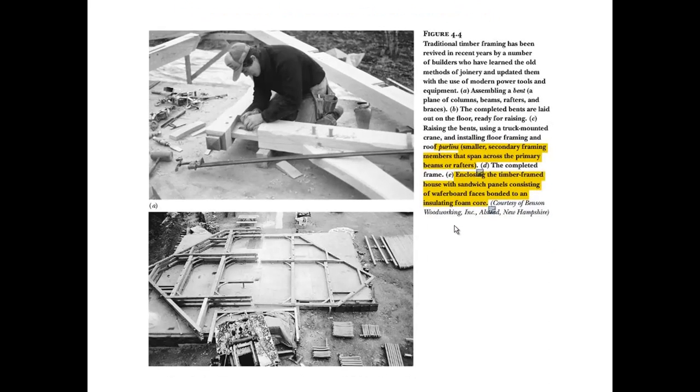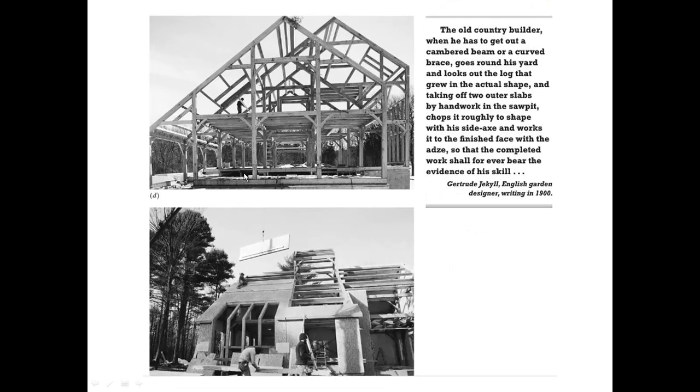We see typical construction of a wood frame residential type building where they're building these frames on the ground. In the old days, of course, they'd have a barn raising. They use what they call pikes to stand these. These layers of wall framing are referred to as bents, and these bents would be stood up in place as the walls go up. Here we can see those bents all up in place and locked in.